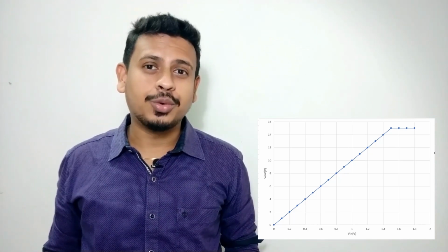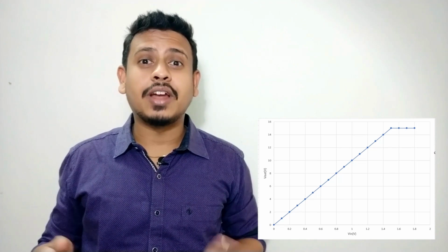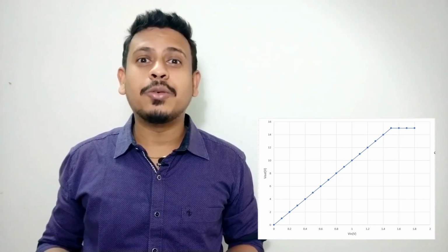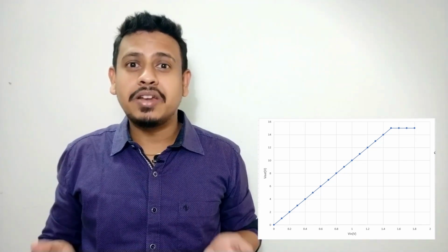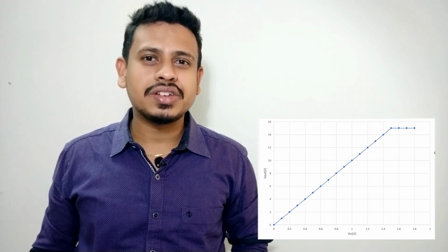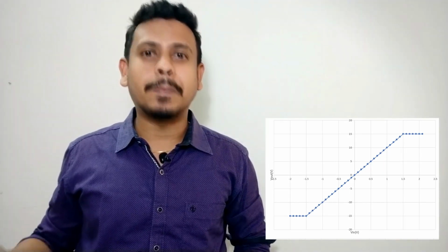In my intro video, you would have seen I wanted to buy the Rubik's Cube at 10 times the value of its original worth, which is 250 rupees, but I gave only 2000 rupees because the money I gave had got saturated. Similarly, for a negative input voltage, any voltage which is beyond minus 1.5 volts, the op-amp output would get saturated to minus 15 volts.